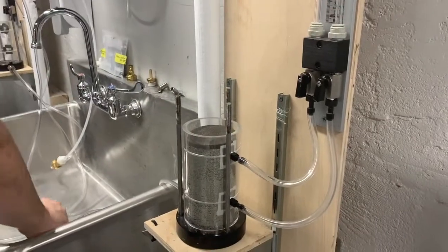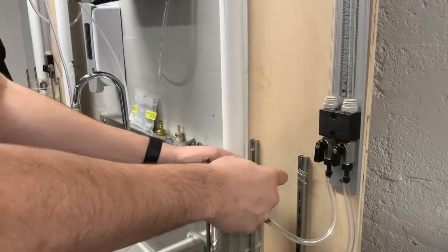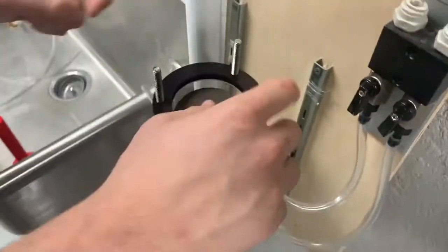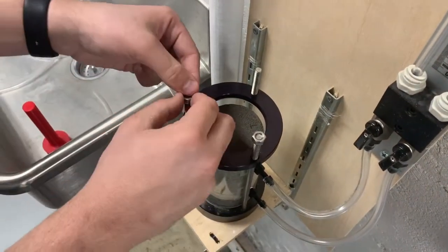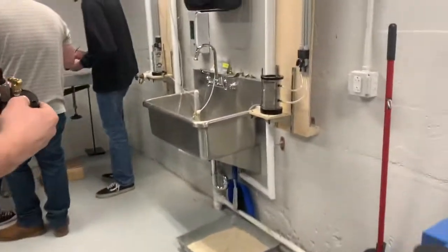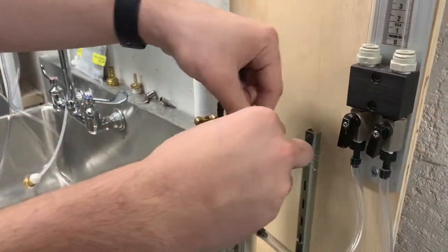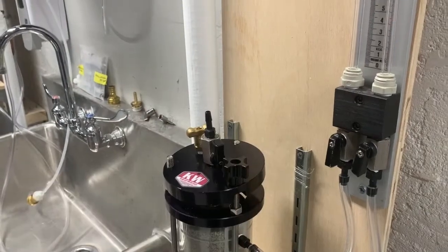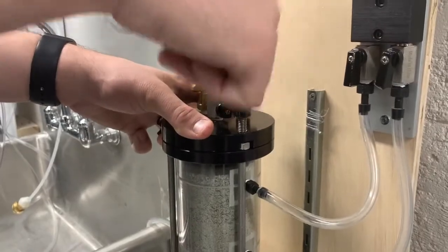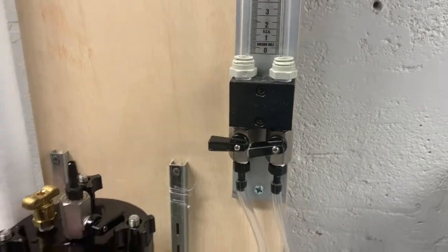Find the black ring and put it on appropriately. Then screw on the silver nuts to hold the ring in place. Place the top of the apparatus on a lid and screw in the caps. We must ensure there is a tight connection here. Make sure each of the valves on the apparatus are closed. Closed is perpendicular to the flow.